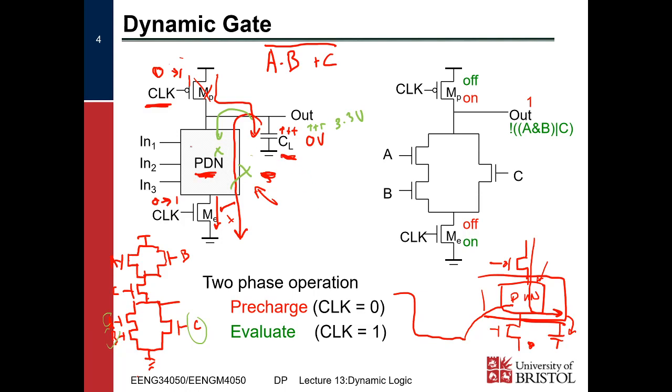All that will change is, compared to the pull-down network, the pull-up network either must be bigger physically, we must have 2 times or 3 times sized PMOS transistors, or they'll have a higher resistance, and so charging up the CL through the pull-up network will be slower. And so for that reason, we always use a pull-down network scheme. Does that answer your question?